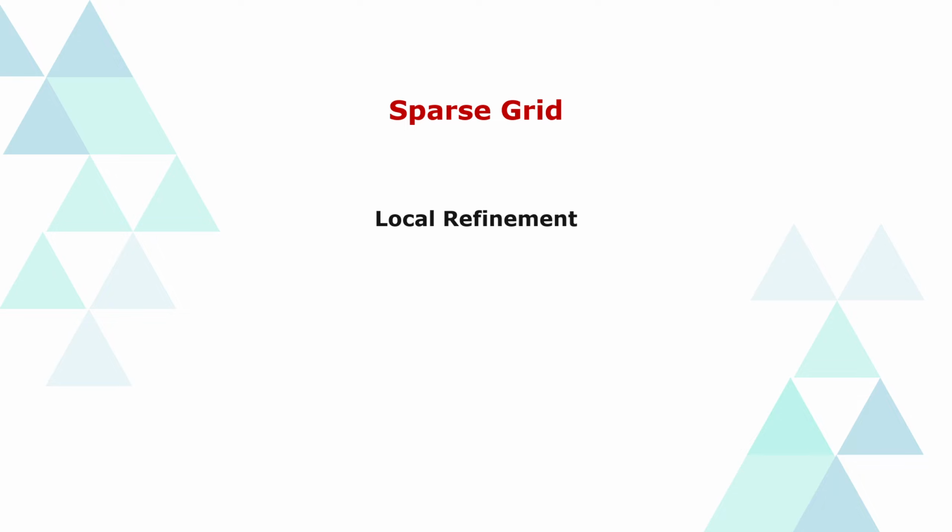This process is called local refinement because it only checks specific areas. Then, it focuses the refinement design points only on these identified areas to improve the accuracy level of the response surface. Since the effort is only on the low accuracy areas, the response surface can reach the required accuracy level faster with fewer design points.